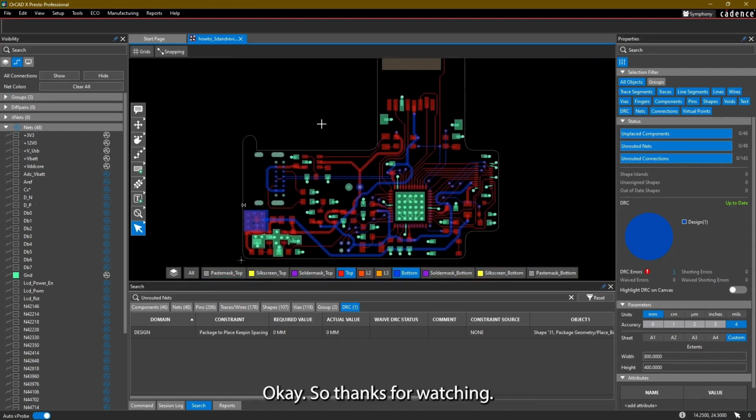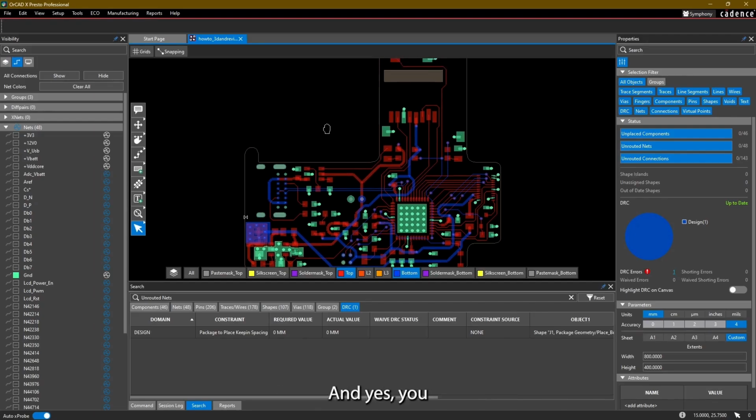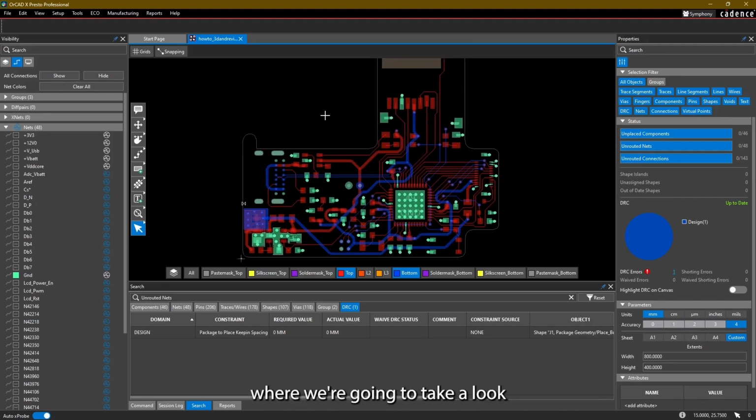Okay, so thanks for watching. This was second pass routing where we did some additional editing of our layout. We added some shapes, we added some stitching vias. We slid around some traces just to make sure that they're looking good. And yeah, see you in the next video where we're going to take a look at the additional DRC options, the 3D view, and also maybe talk about doing some silk screening.